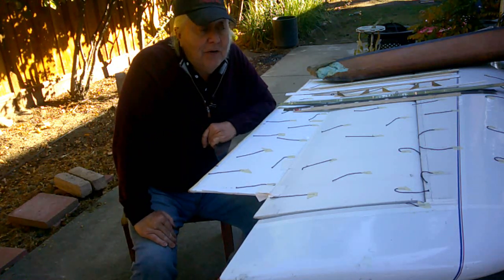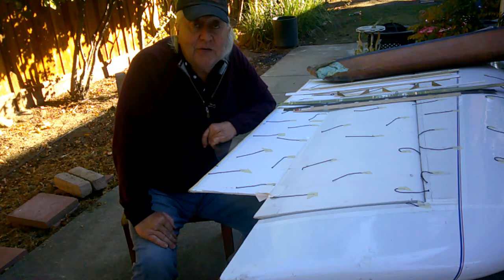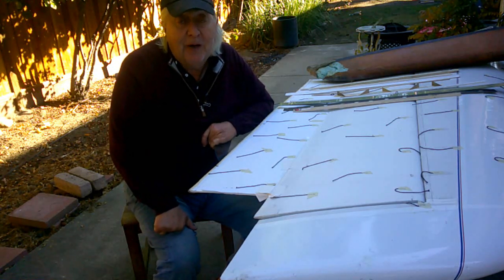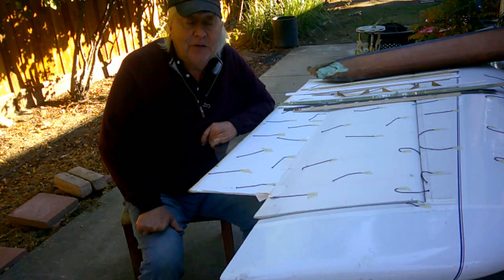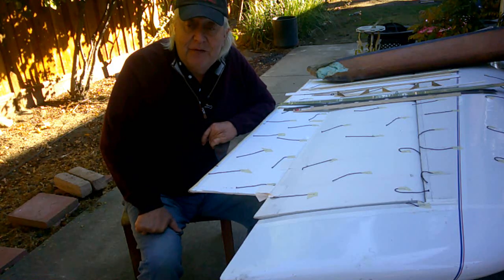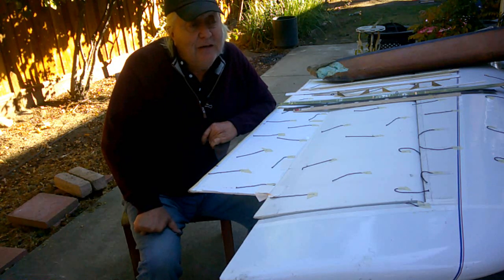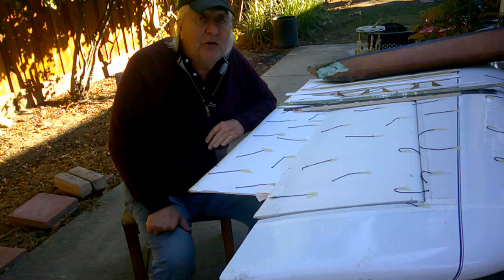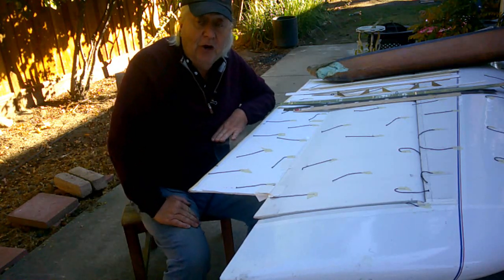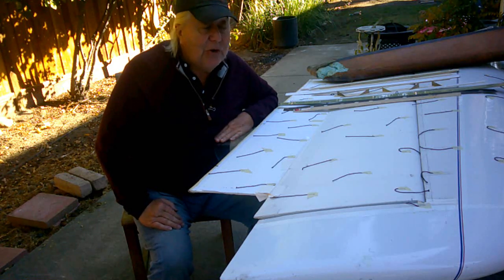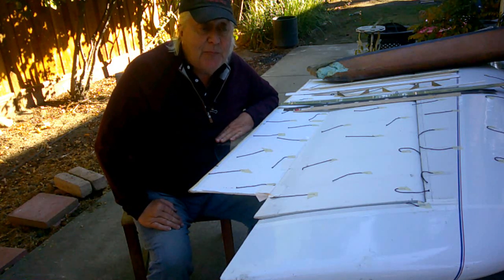Now, on foot-launched aircraft, we need a stall speed down around 20 miles an hour. So just simply decreasing the wing area, bad plan. Very rapidly, to get to the aspect ratios we want, you end up with not enough wing area to actually take off. Your wing loading is too high. Your stall speed is up around 30, 35 miles an hour. You can't run to get it off the ground. Make a good ultralight sailplane that you tow, but you ain't going to run it off the ground. Okay, so you increase the span.